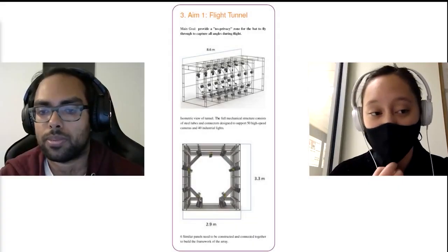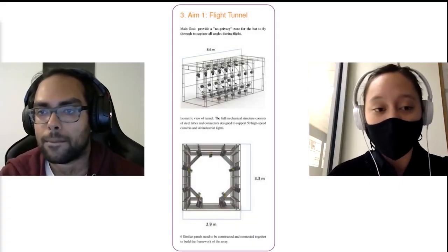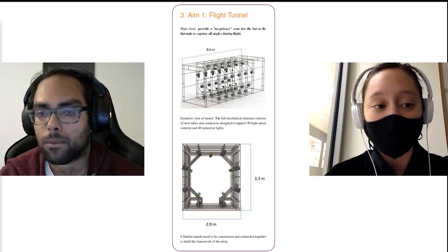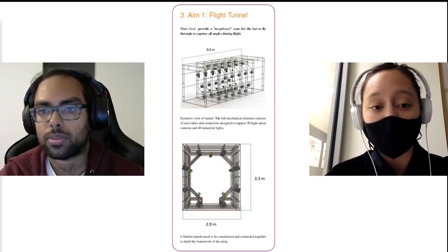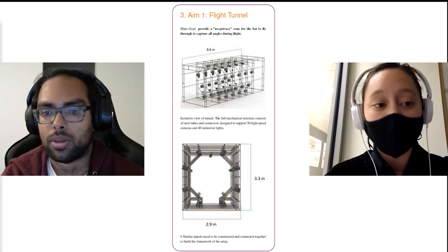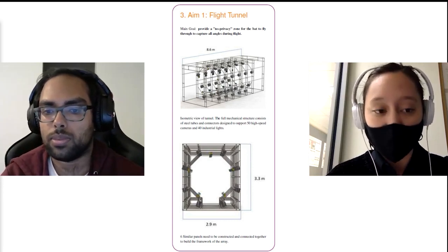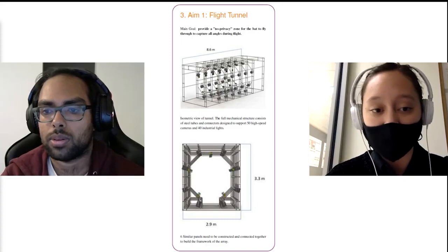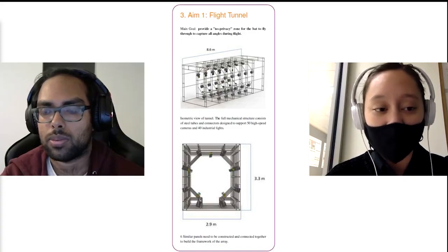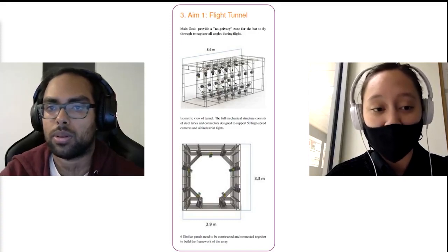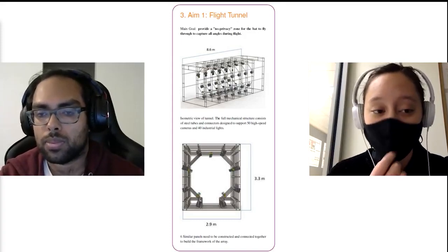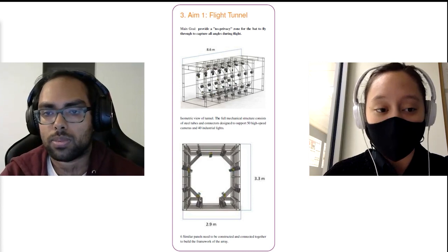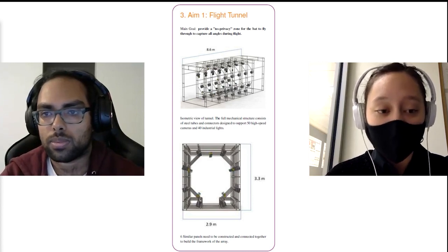The camera tunnel array is basically what it sounds like. It was previously designed in SolidWorks by a design team for their senior project. It will be made to support the full load of 50 high-speed cameras and 40 industrial filming lights. The structure is broken down into 8 panels for ease of assembly and camera access. It consists of 1-inch outer diameter steel bars and steel pipe connectors that can be bought from mcmaster.com. When it's assembled all together, it will form the shape of a tunnel, hence the name.